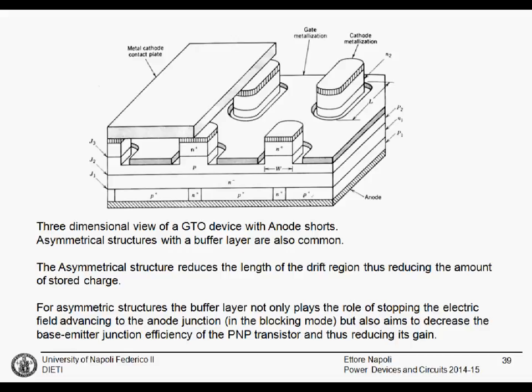This buffer layer is the one in charge of stopping the electric field that will go like this in the blocking state.